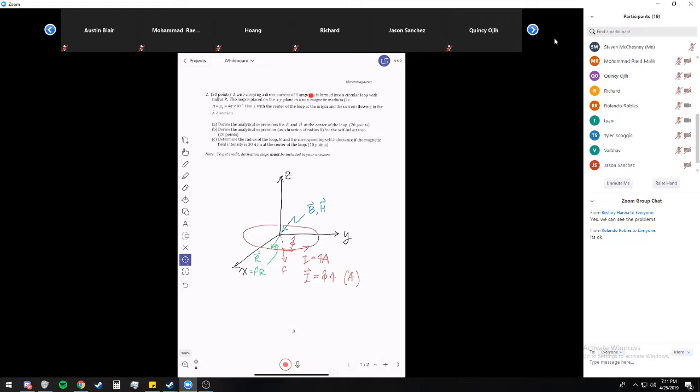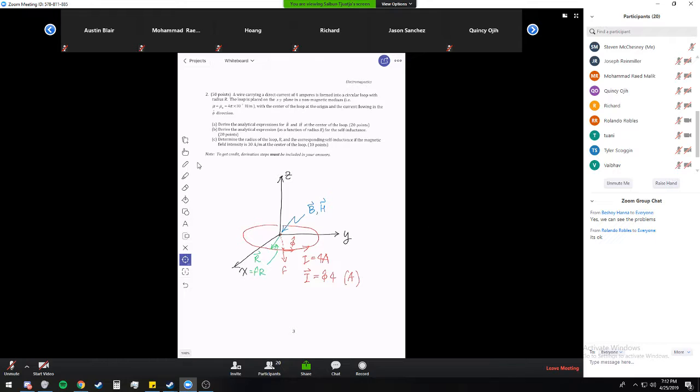You can use the Biot-Savart law, which you can solve directly. This is a simpler problem, so you can use the Biot-Savart law. Another, a little more complicated law is the closed integration of H equal to the current I, which is Ampere's circuital law. Because it's magnetostatic, it's easier to solve using the Biot-Savart law, so I'm going to use the Biot-Savart law to solve this problem.